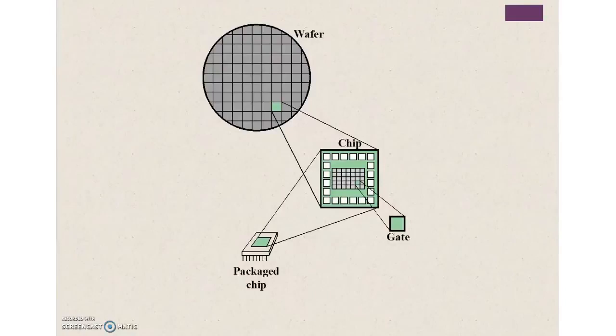This figure depicts the key concept in an integrated circuit. A thin wafer of silicon is divided into a matrix of small areas, each a few millimeters square. The identical circuit pattern is fabricated in each area, and the wafer is broken up into chips. Each chip consists of many gates and/or memory cells, plus a number of input and output attachment points.